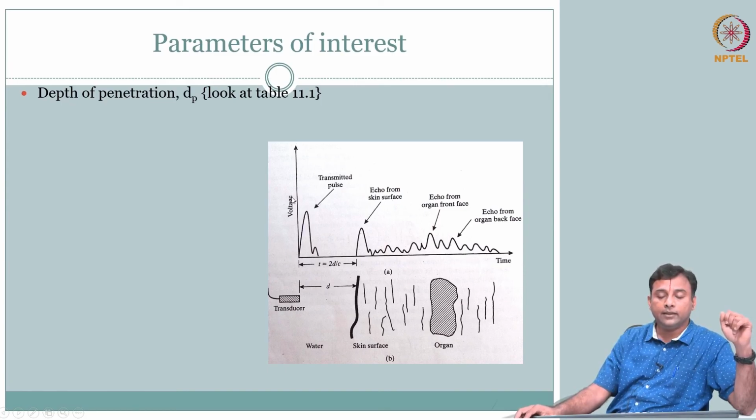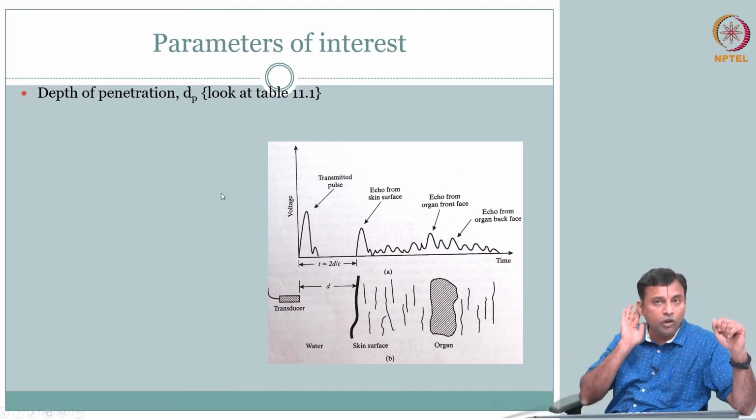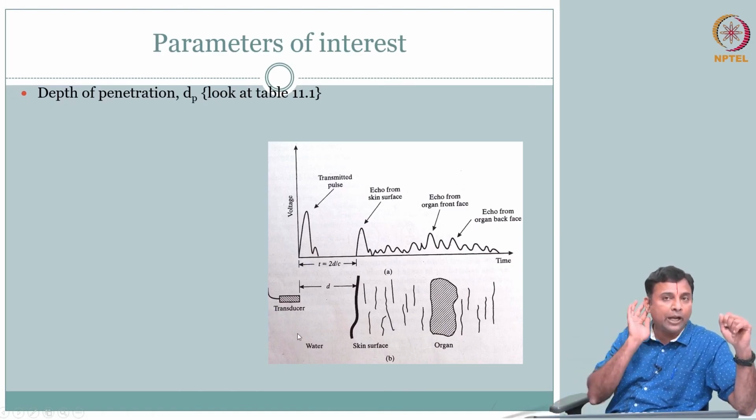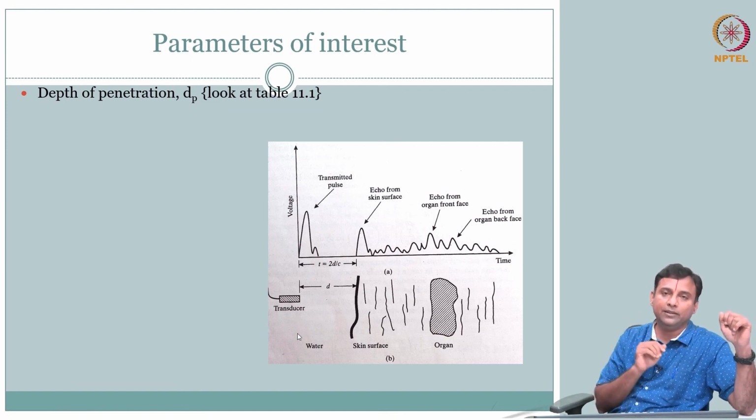So now what are the things of interest? First thing is depth of penetration. What is that? Why is that important? So how long should I listen? I can keep on listening because the wave is going and it's getting reflected and the echo is coming. But how long should I listen to the echo before I send the next pulse?